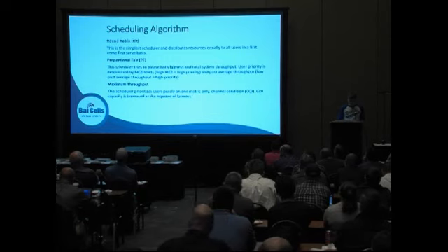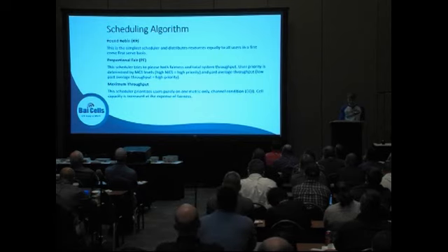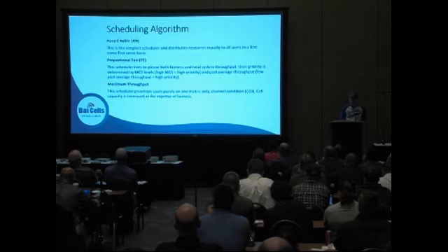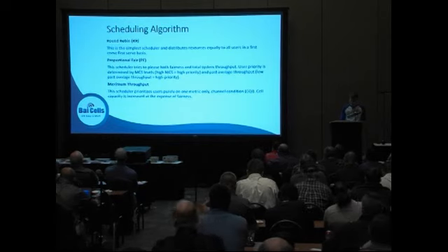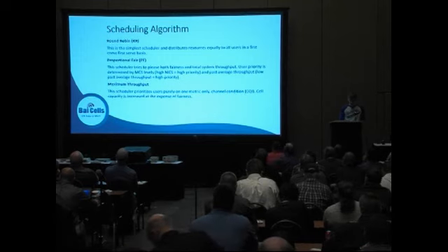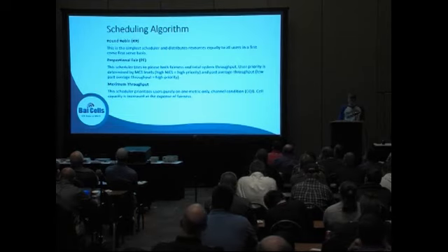I think the one that would be of most interest is maximum throughput, because this will basically assign the highest priority to the best connected users. So if you're looking for the best total aggregate throughput, maximum throughput would be the best scheduler to select. The other one, PF, is a little more complex, but it averages what throughput they're getting and also puts the MCS levels into the equation. So it tries to be a little more fair with that.